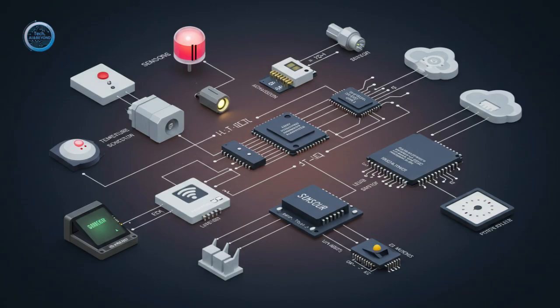For example, a 10-bit ADC, which is pretty common, can represent the analog voltage range as one of 1024 distinct digital values from 0 to 1023. So it turns the ramp into a series of steps. A very good way to put it.